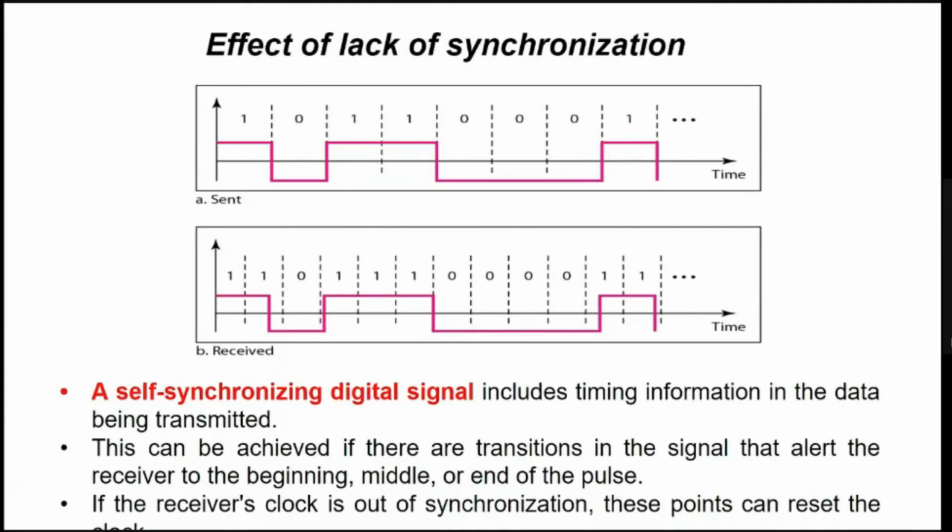You just calculate the data element and the signal element. Data element divided by signal element is the R value. So what is the data element here? Are you listening? What is the signal element here in the first diagram? So here, in the first diagram, the data element is 1 and the signal element is also 1. So 1 by 1, the R value is equal to 1.